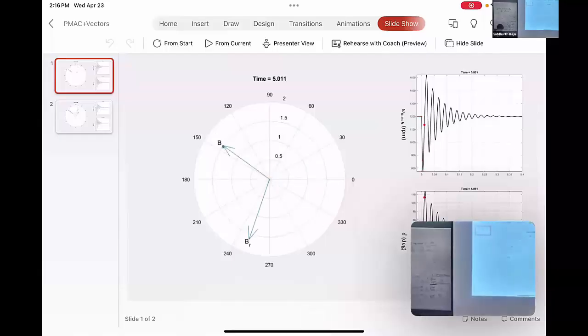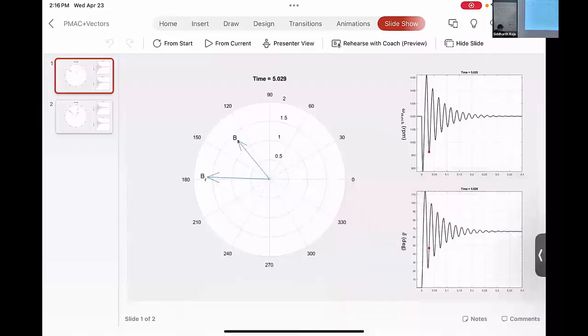The setup that we have is a motor that's already rotating at steady state at the synchronous speed, and then I'm applying a sudden load torque. So if you go to this diagram here, initially it's rotating at 1200 RPM, and as soon as I apply a load torque, the speed starts to dip. So this is exactly for the 6-pole case that I gave in the homework.